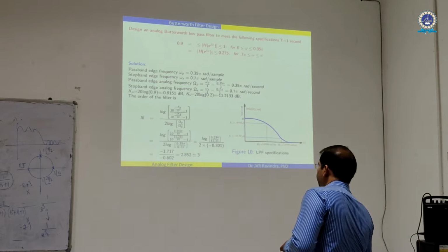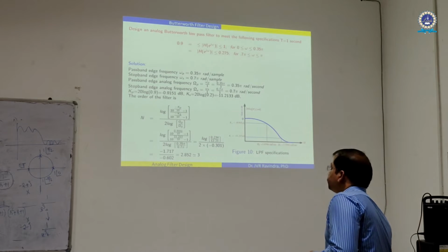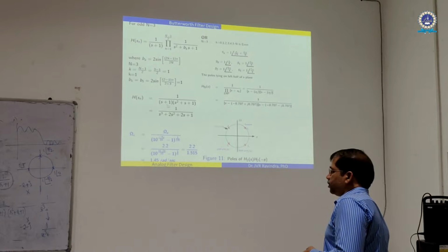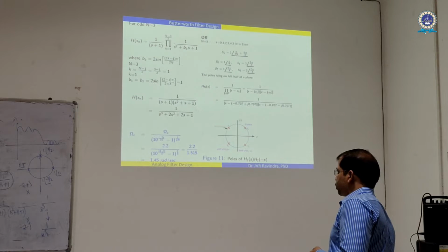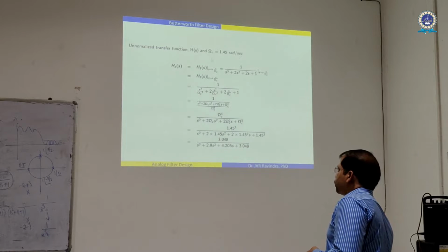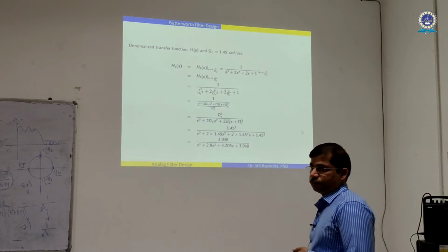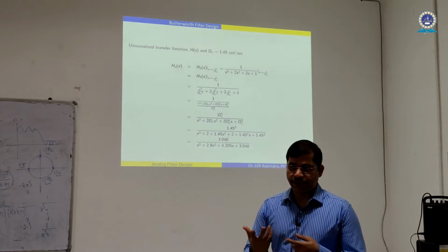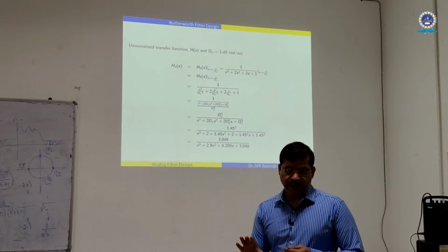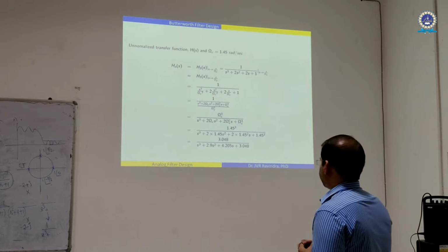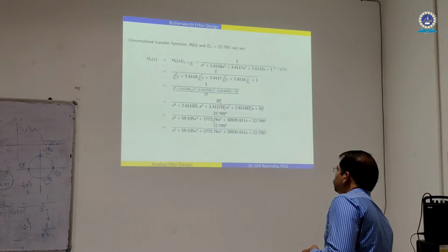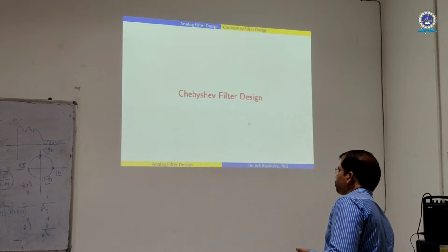And this is one more problem wherein I have chosen n equal to 3, the same or similar values. And this is the transfer function. Directly you can get it, 1 by s plus 1, s square plus s plus 1. And the omega c value you got is 1.45, and again you transform that, so you get the other transfer function. And here also the realization does not exist for analog filters. I'll skip the problems. There are many complex problems that I have chosen.